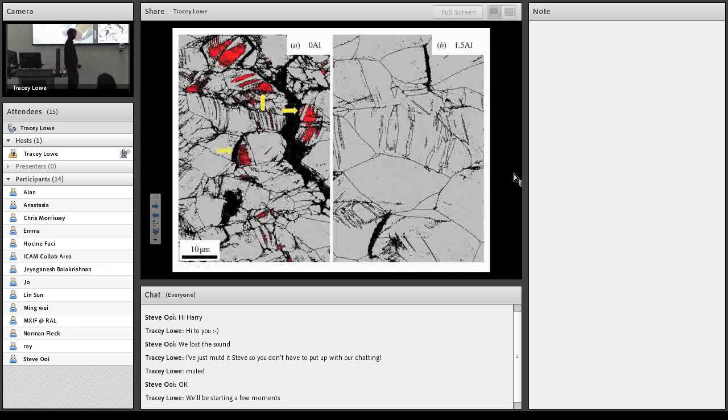Now, in the case of the low aluminium alloy, we also pick up phase transformation. This is epsilon martensite, hexagonal close-packed martensite forming. So with sufficient deformation, you actually get epsilon martensite forming. It doesn't in the case where we have a large stacking fault energy. So what we did was we examined these by doing focused ion beam, machining out and putting it into the TEM to see what those facets actually are.